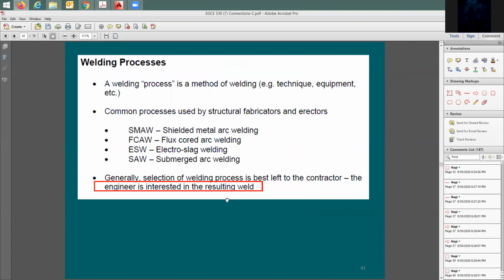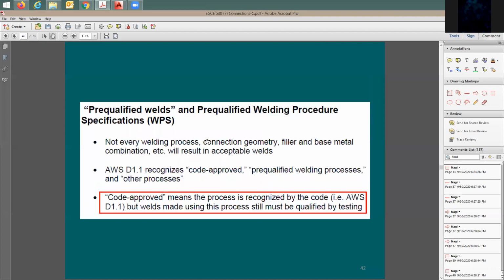Welding is done when we join two plates or when we melt metal to join them, like the metal from one plate is melted to join the other. Soldering is when you use a third metal to join two metal objects. Usually a small wire or a small connection is used for soldering. Generally speaking, if you're doing structural steel, it's got to be welding. Soldering is for small pieces, when you're soldering a wire to maybe a connector or something like this, where you don't really need to melt the base metal.